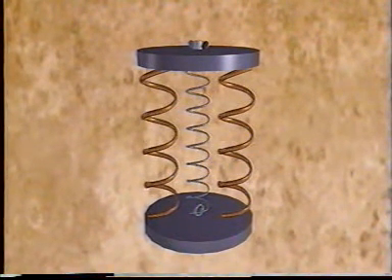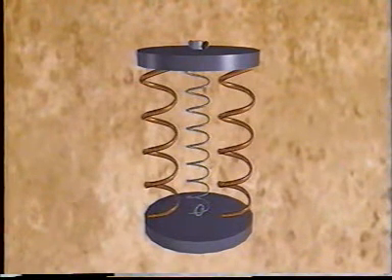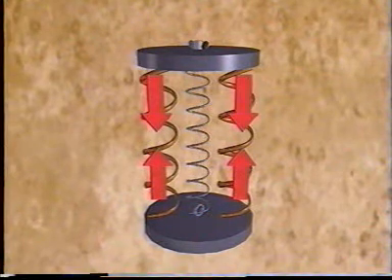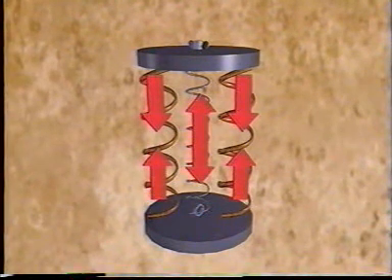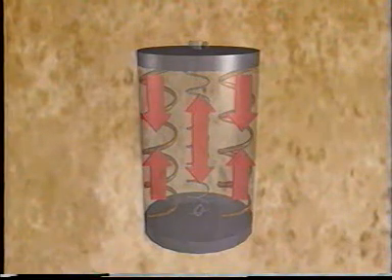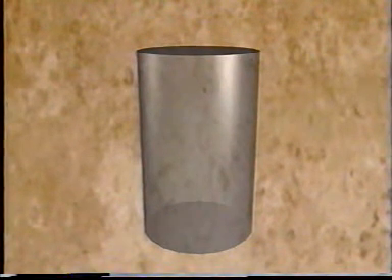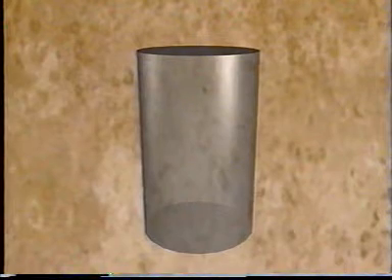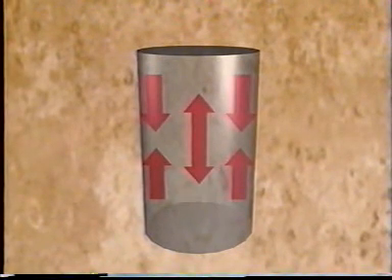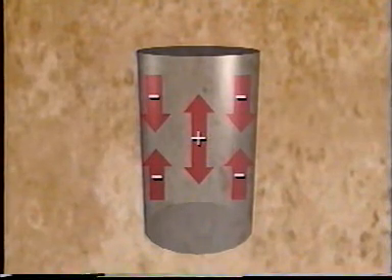Now the assembly of parts, a visual model of internal stresses, is balanced and stable. Two compression springs hold the blocks apart. One tension spring pulls them together. If we visualize this model of one tension spring on the inside and two compression springs on the outside as a cylinder or rod, the balanced stress system within the cylinder might look like this. Remember, tension is positive. Compression is negative.